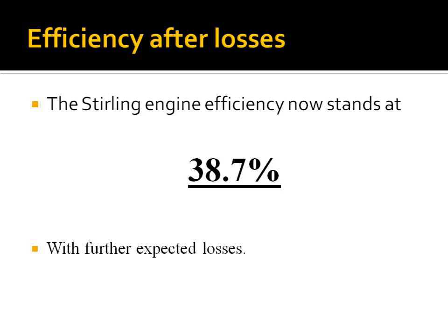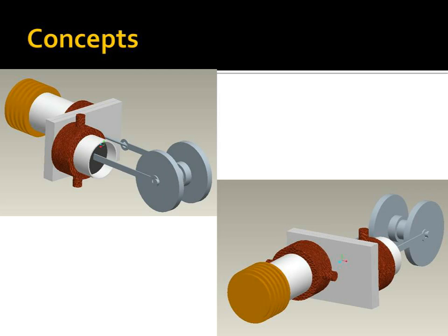So your question is, what sort of tolerances do I need to work with? Well, once I go down to the workshop, there's 2 real critical parts that I need to focus on in terms of tolerancing. The power piston and the power cylinder, there needs to be tight tolerance there in order to create an adequate seal.